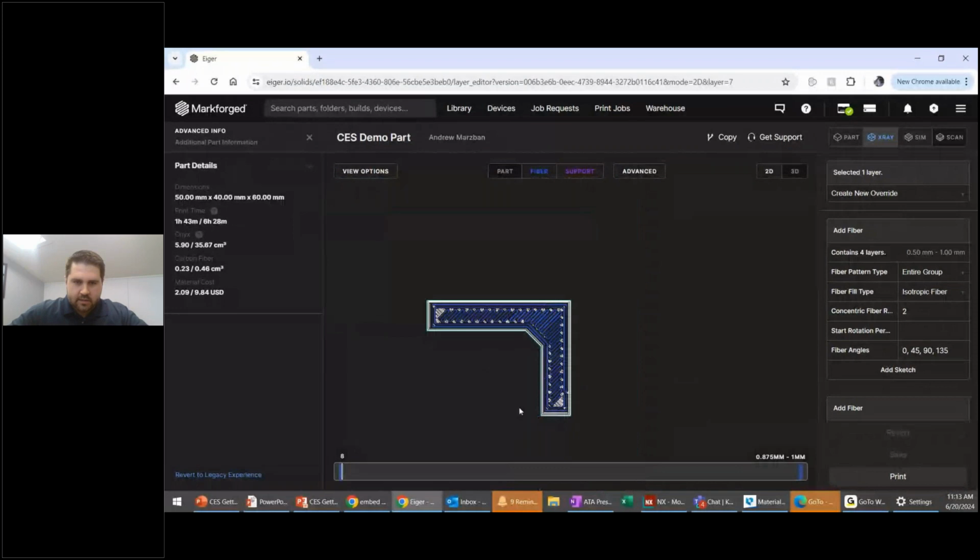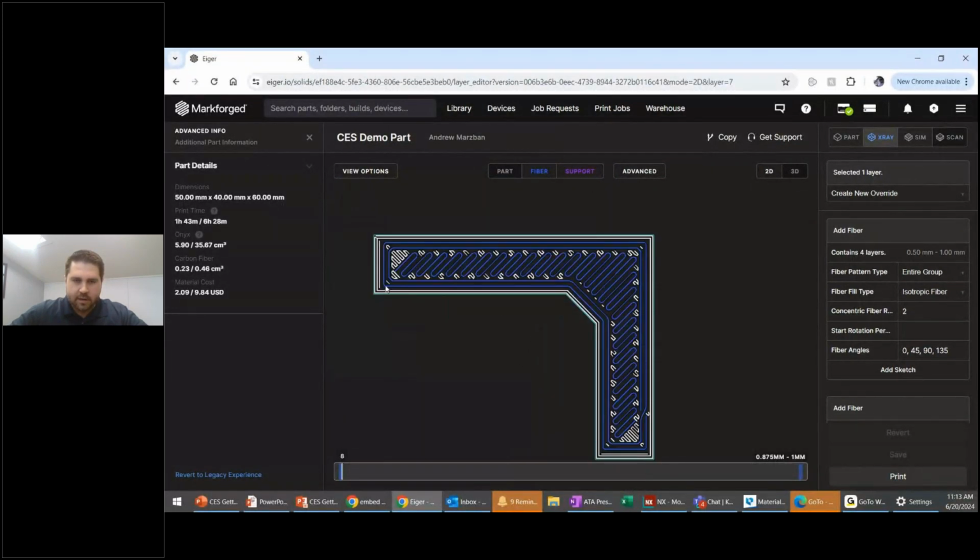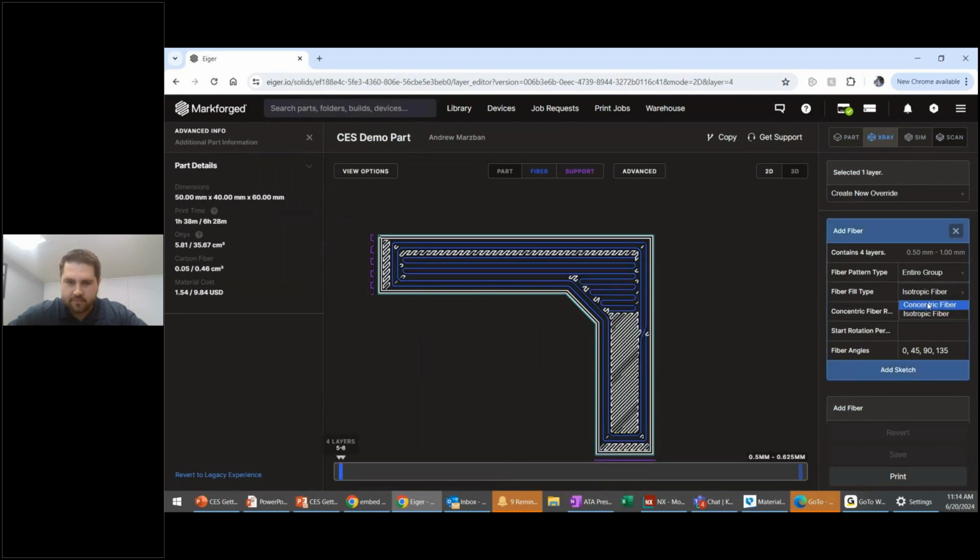So we want to make this part resistant to bending. And if we're talking about bending, see now we're looking at the side of the part. So imagine this plane right here is going to be pinned down to something, maybe bolted down, and then this part sticking up is going to receive the force. So again, we have a bending situation where straight through the middle of the part here, we have our neutral axis and we don't really need carbon fiber there.